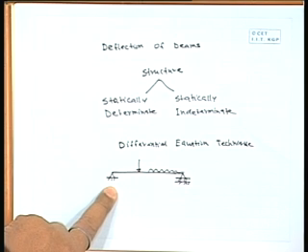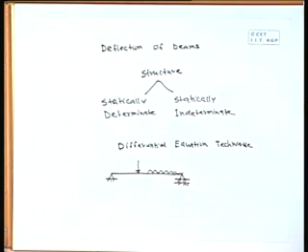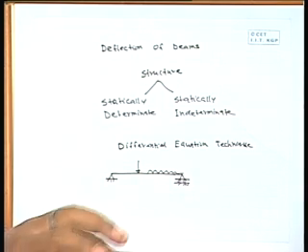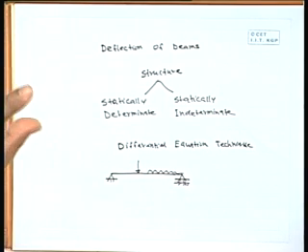Now, if we make the left hinge support a roller, what will happen? The number of unknowns will be less, 2, and the equations will be more. In that case, the structure will not be stable. So, all the time we can't make it as minimal as possible. A minimum number of restraints is necessary, because any structure we want to fix in space will require some support.